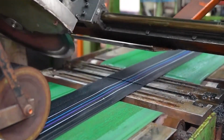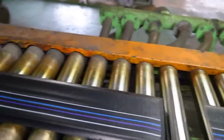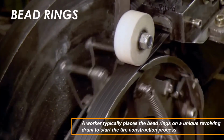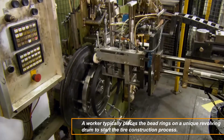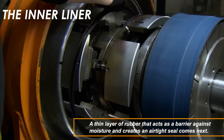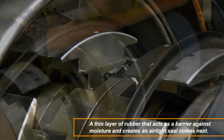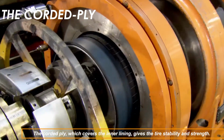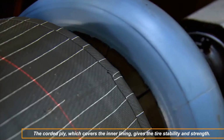Are you ready for the exciting part? At last, every component of the tire comes together. A worker typically places the bead rings on a unique revolving drum to start the tire construction process. The inner liner, a thin layer of rubber that acts as a barrier against moisture and creates an airtight seal, comes next. The corded ply, which covers the inner lining, gives the tire stability and strength.